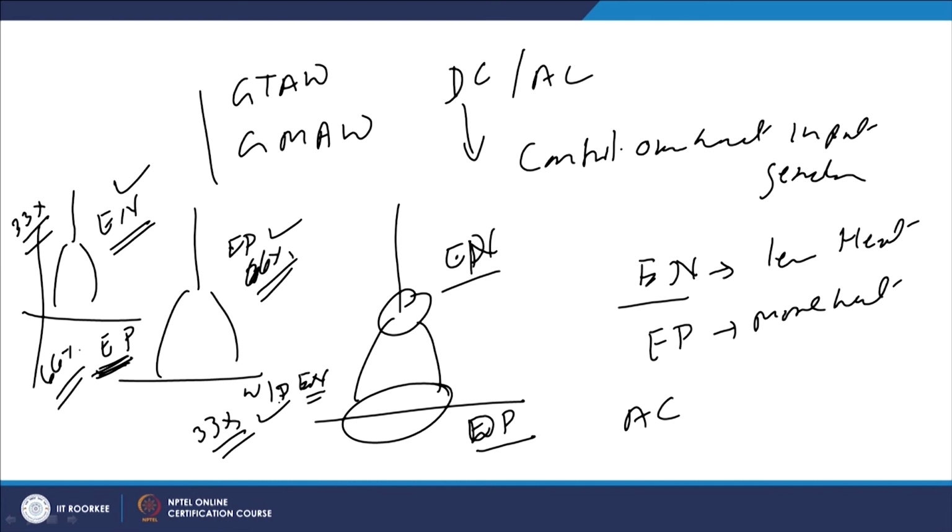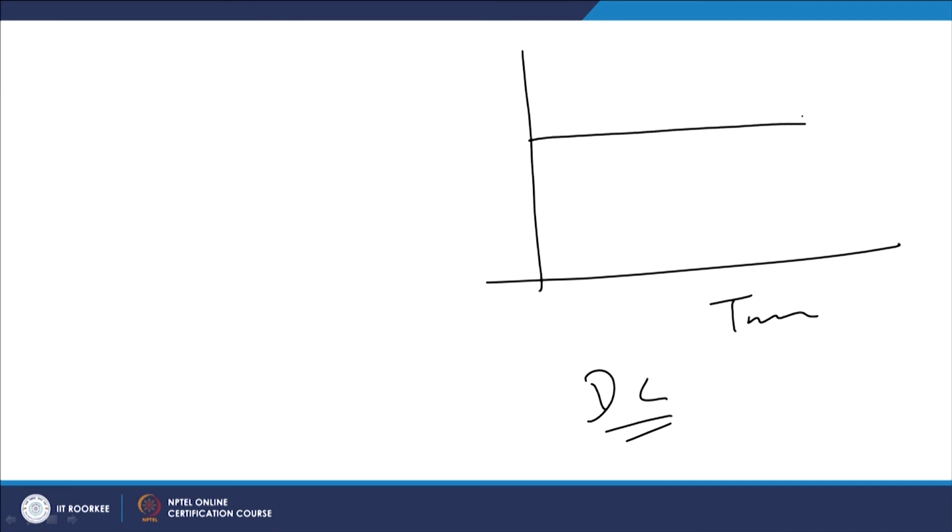So, the amount of heat generated will be affecting the dilution as well as the cooling rate, and that is why we select the polarity suitably. Now, another aspect related with this is pulsation. In the normal case, the current magnitude remains constant. In simple DC current, as a function of time, the current magnitude remains constant.